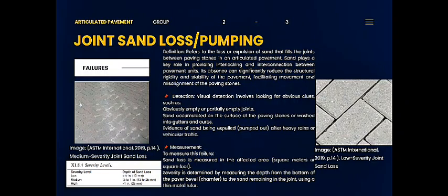Severity levels. Low: less than 1/2 inch or 13 millimeters. Medium: between 1/2 and 1 inch, or 13 to 25 millimeters. High: greater than 1 inch or 25 millimeters.